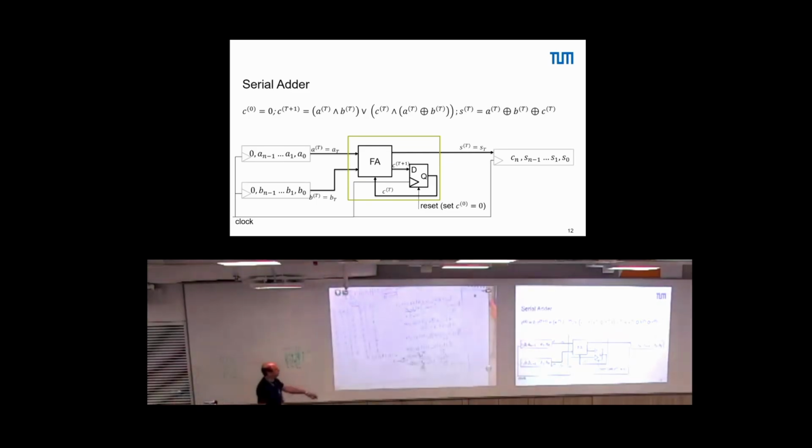so if you apply a 0 for the carry in, that means the XOR is just a buffer, it's just forwarded. Whatever the input is, the output is, because 1 XOR 0 is a 1, 0 XOR 0 is a 0, so this is just forwarded. An AND gate, if this is a 0, the output will always be 0. So this part here just vanishes. The lower is already 0, so only the upper is propagated. Whatever comes out here is AI and BI, so this is just the half adder that's left if we put this to 0.